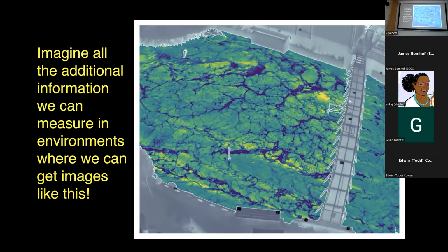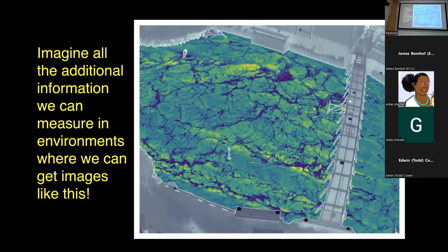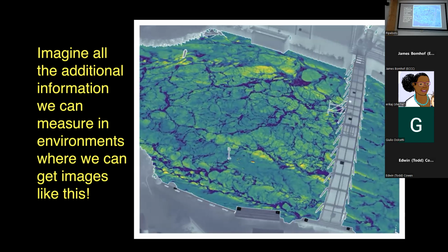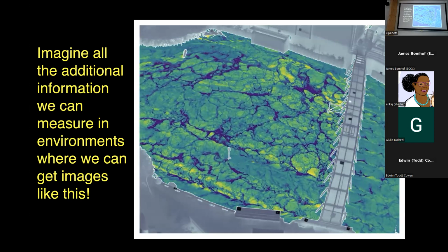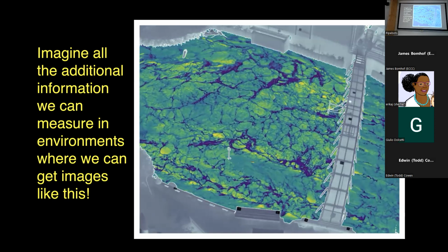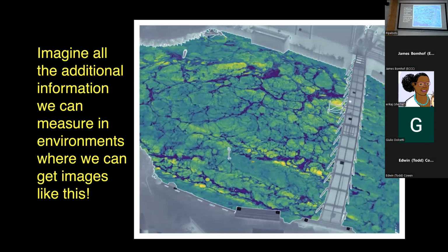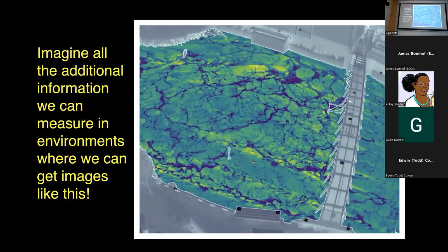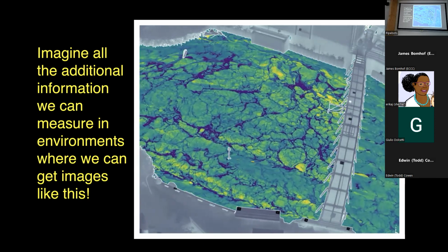Okay. So have you taken into consideration, you talked about the velocity gradient tensor, the wall normal components can have quite an impact. Have you looked at any methods which can capture that, like holography or tomography, to see if you can better those results a little bit? So you mean things like the du/dy coming off the sidewall boundary layer? No, coming from the base, so the W component.